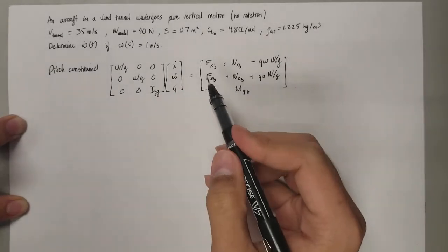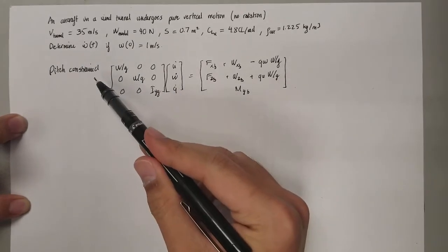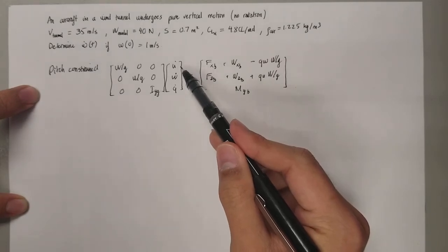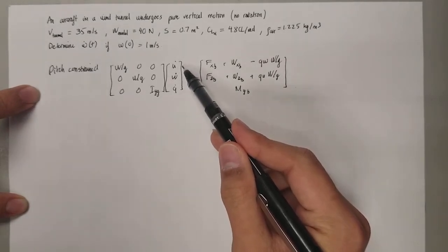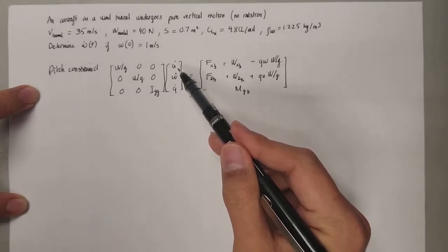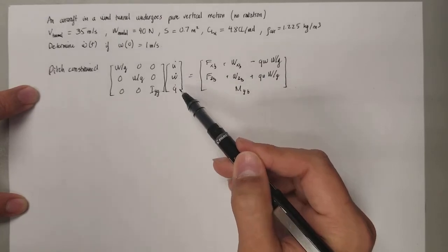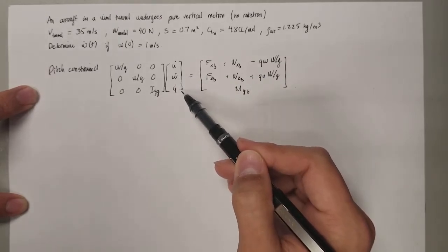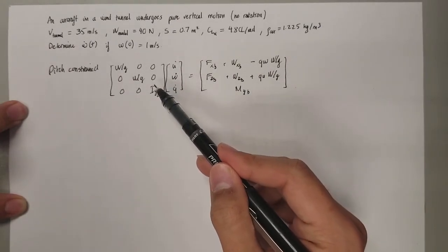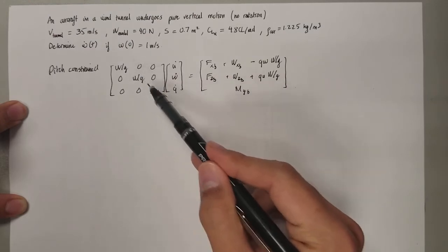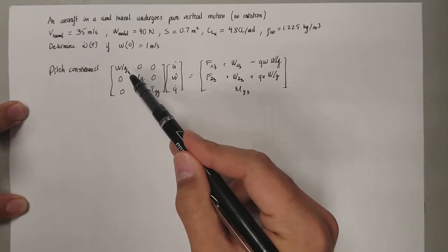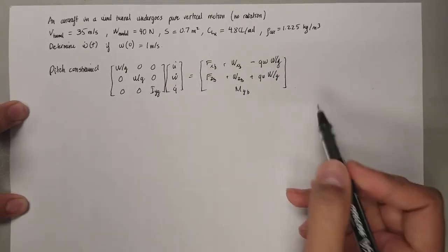Okay, since our aircraft is constrained in pitch motion, there are only three terms that can describe the motion of the aircraft: the rate of vertical translation, the rate of horizontal translation, as well as the pitch rate of the aircraft. If you look at the 12 equations of motion that were given to you during class, you can just rewrite them, with terms corresponding to the given matrix.